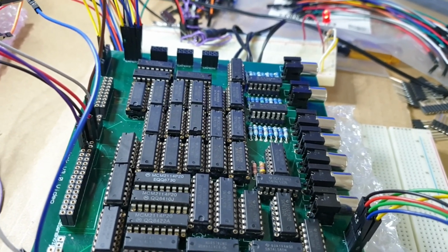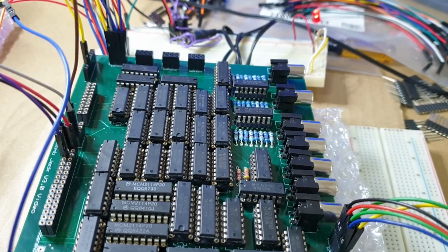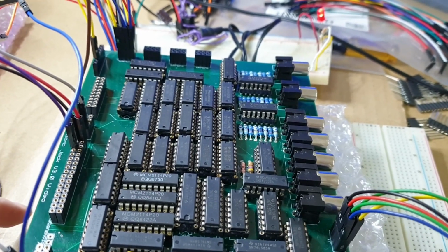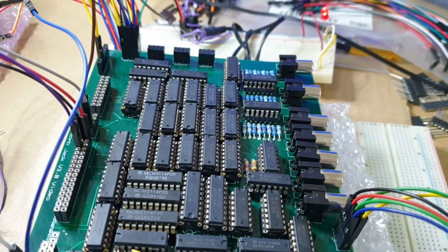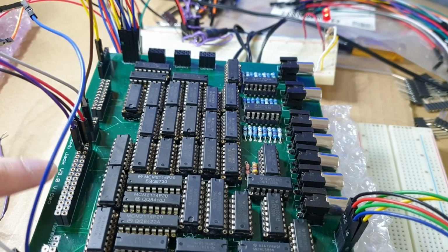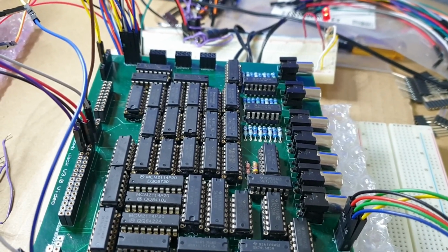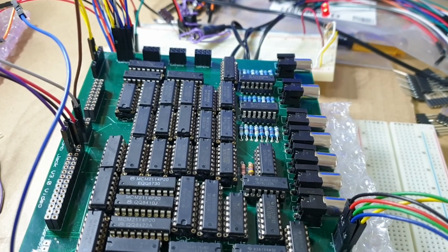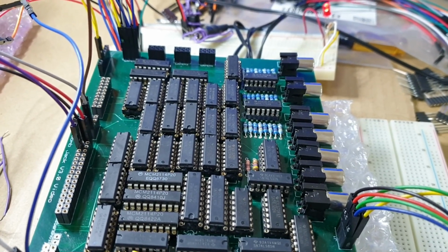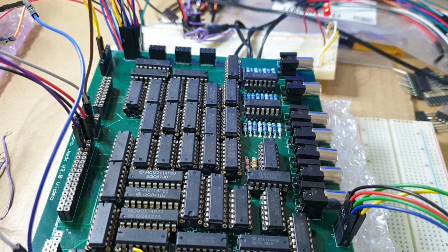So what I think I'll do is that I'll have the right-angled IDC connectors for the interboard connects, but I will also have input headers for the top end of the memory bus, perhaps, or just continue the ribbon cable upwards. That would also be one thing to consider.